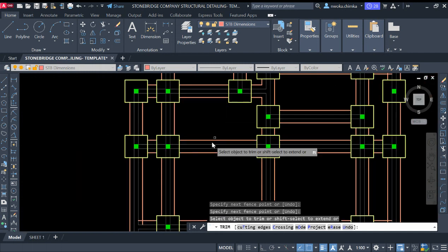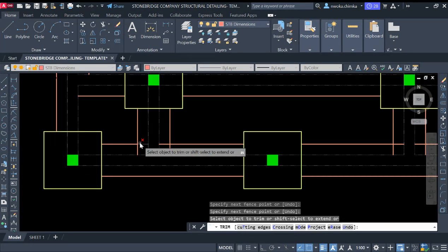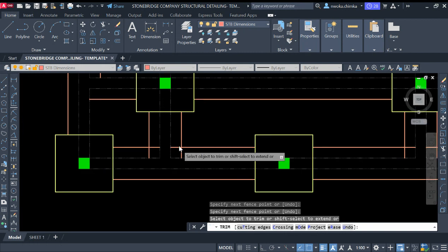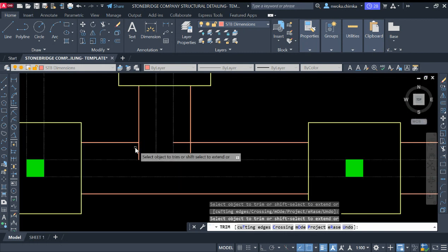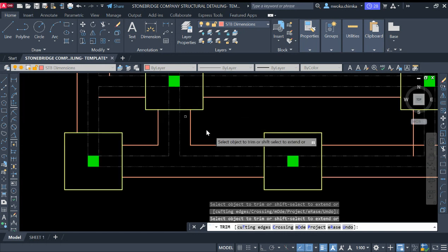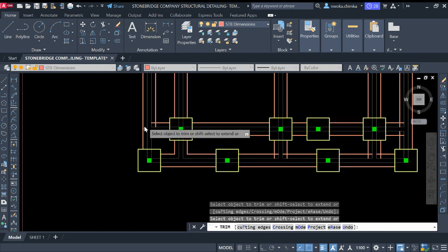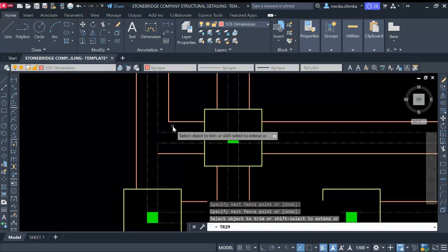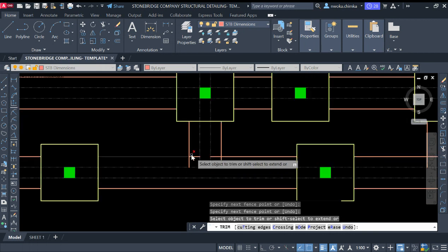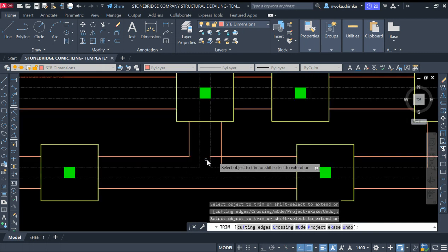And also that, so if you have any kind of flaws like this, that means concrete will not flow very well. So to show it directly on your plan view, you show that anyone reading this structural drawing knows that when they cast this concrete at this place, concrete is meant to flow all the way down to this place. Okay, so do the same thing here again and here also. So remove the area that has this kind of shape to form this shape which you're about to form now.